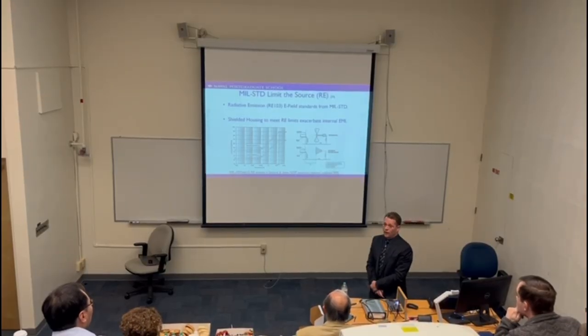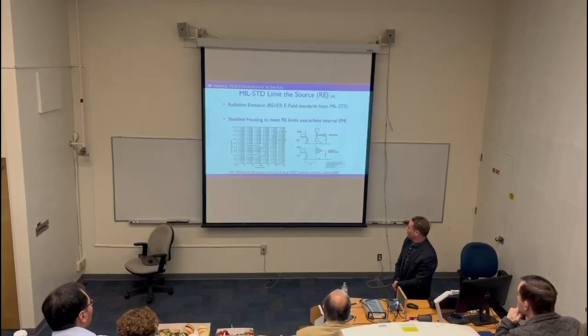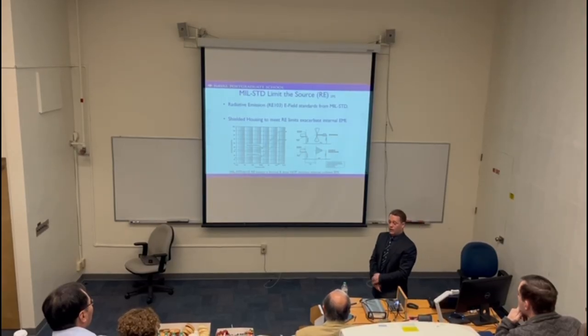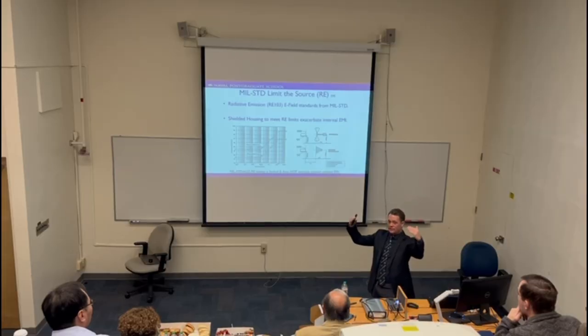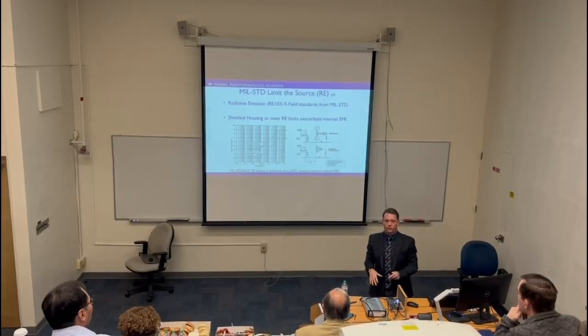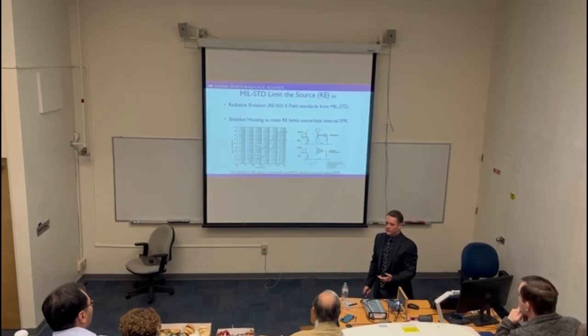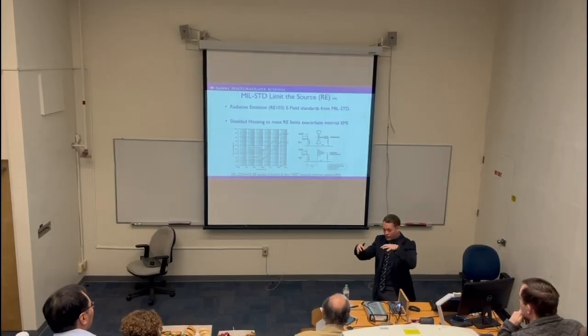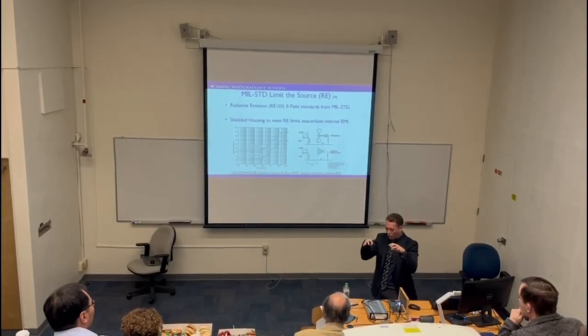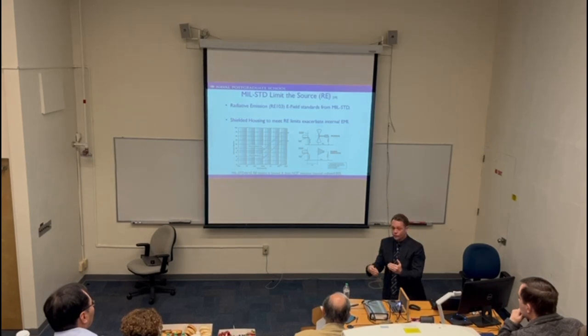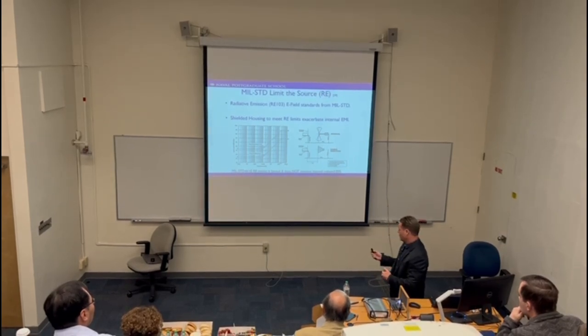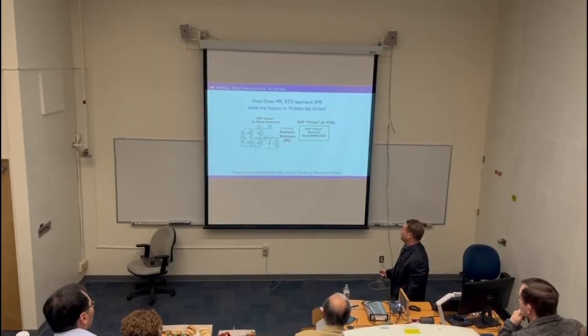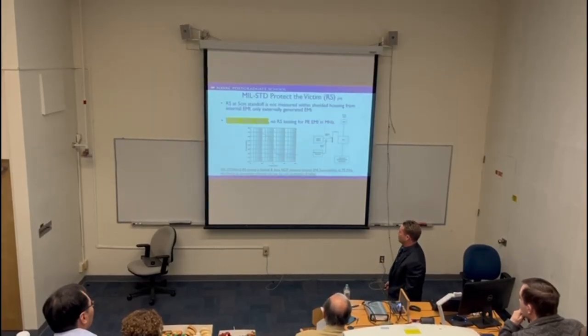The problem is the way that a lot of people pass MIL-STD-461G is, okay, we just need to make sure that our radiated emissions are not at this level. So let's just put a little Faraday shield over top of it, house it with a chassis that's grounded. And yeah, as far as 461G is concerned, problem solved. But now you have basically a miniature reverberation chamber. Now all that energy is traveling around, bouncing off the walls, coupling to all the inner circuitry. Does MIL Standard test for that? Absolutely not. It's only looking at the boundary of that housing. And so that is certainly a vulnerability that is not seen through typical radiated emissions testing.